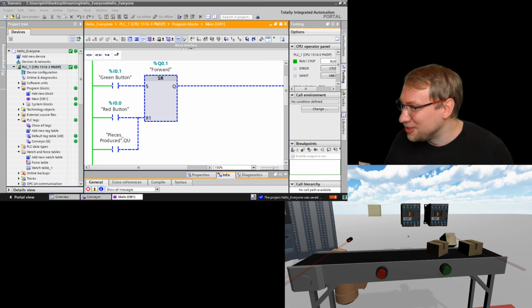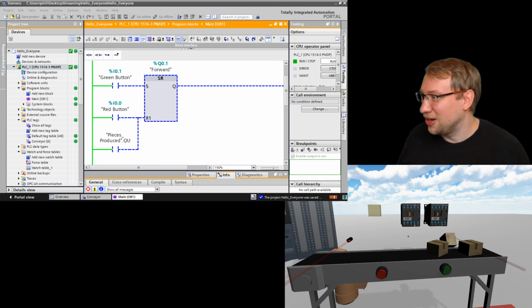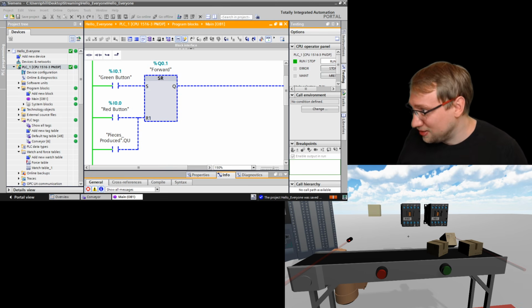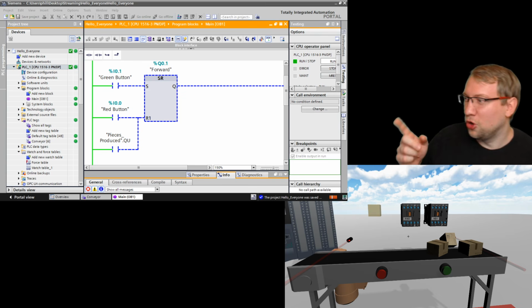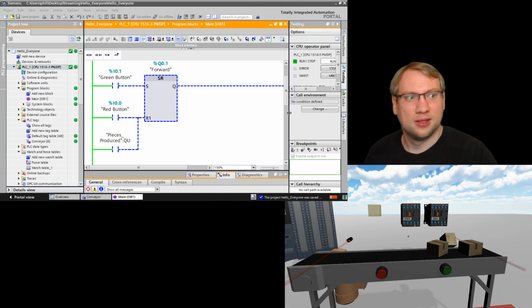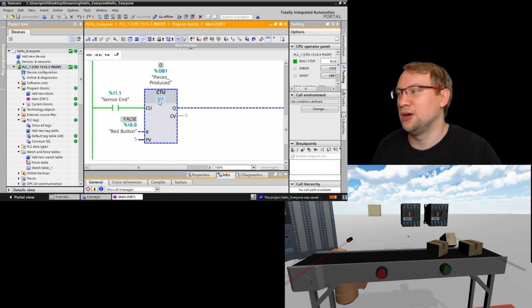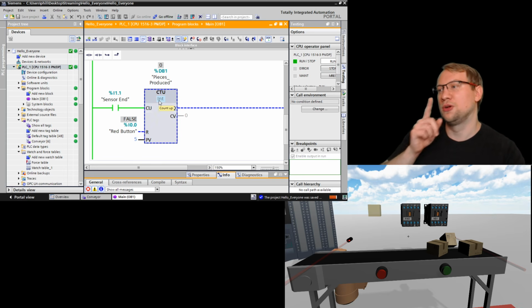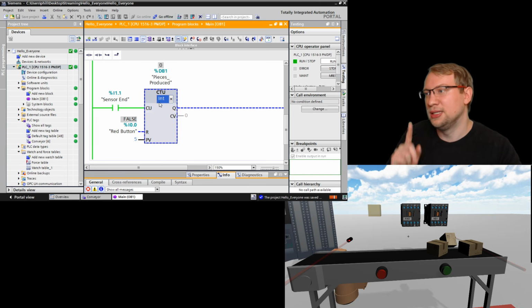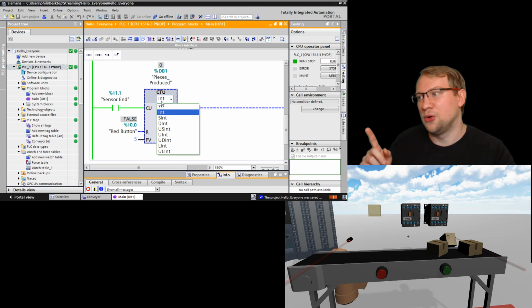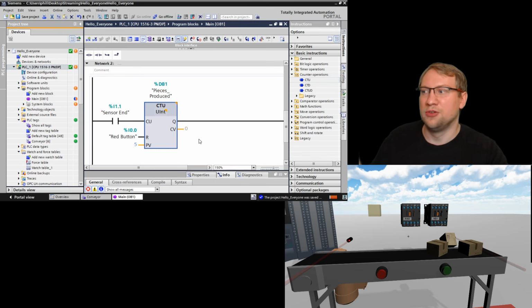I had a problem with the up and down counter. I count up, down, where the counting down only stops at 0 and not lower. Kobe, that could be because you can set the data type. If you have your counter, you can select the data type. If you select uint, for whatever reason, it could happen.